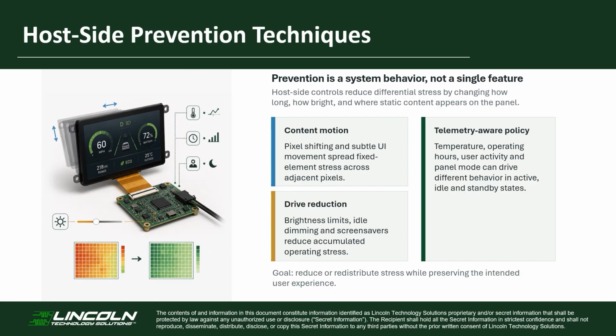Telemetry-aware policy makes these behaviors more intelligent. Temperature, operating hours, user activity, and system state can determine how the display behaves during active operation, idle periods, or standby. The goal is not to make mitigation obvious to the user. It's to reduce or redistribute stress while preserving the intended experience. Many of these strategies are most effective when they're considered during user interface design.